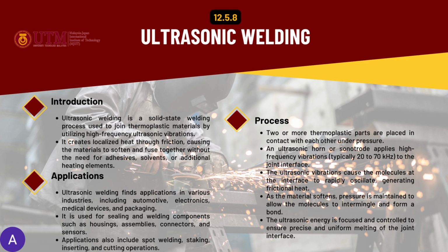So, the working process for ultrasonic welding is: two thermoplastic parts are placed in contact with each other under pressure, and then an ultrasonic horn or sonotrode applies high frequency vibration. The ultrasonic vibration causes the molecules at the interface to rapidly oscillate, generating frictional heat. And then as the material softens, pressure is maintained to allow the molecules to intermingle and form a bond. Then the ultrasonic energy is focused and controlled to ensure precise and uniform melting.